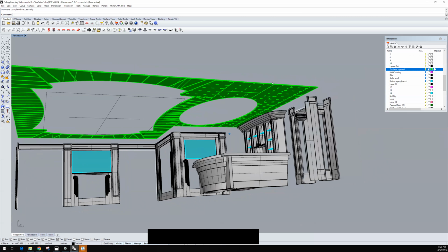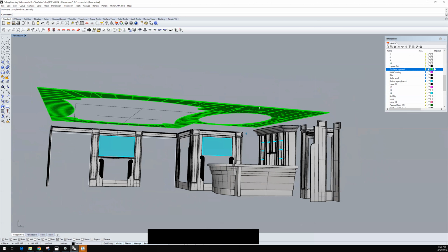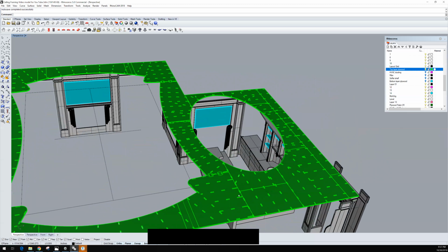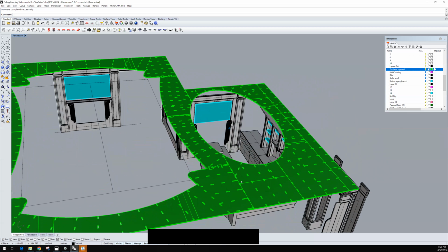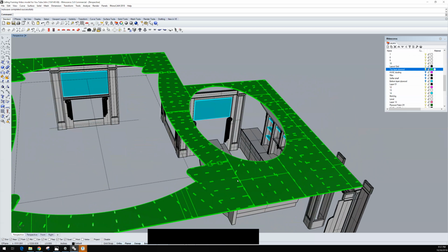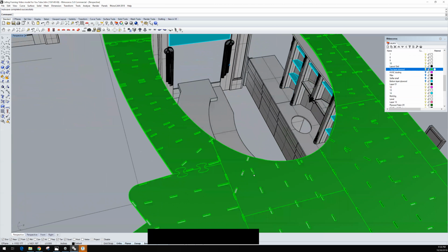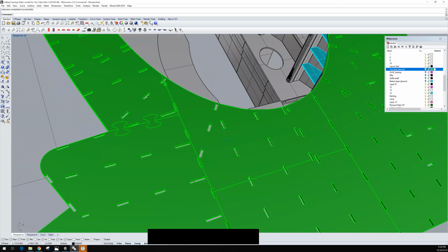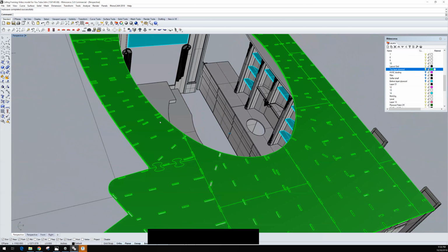And the way that we did that was, if you look down on this green layer, all of these sections here are fabricated out of 4x8 sheets. They're actually 47.5 inches across, so we were able to cut the joint line and these pockets. And these pockets, what they do is they accept another piece of plywood, which is in a rib or a frame stage that is going to go around the ceiling. You'll see that here in a second.